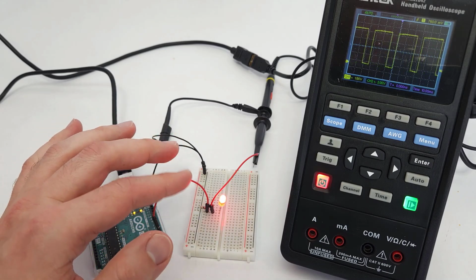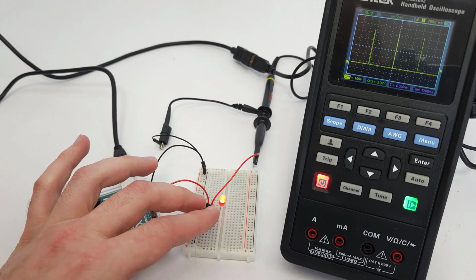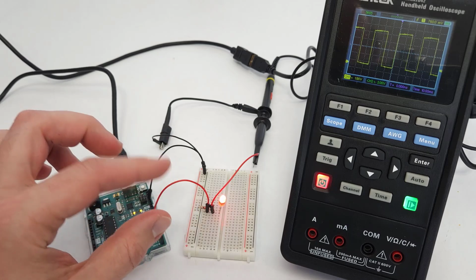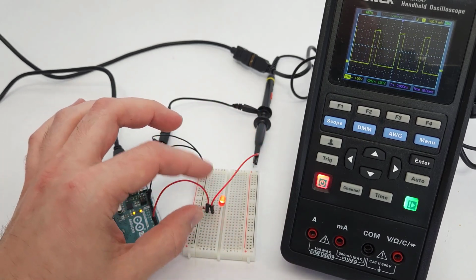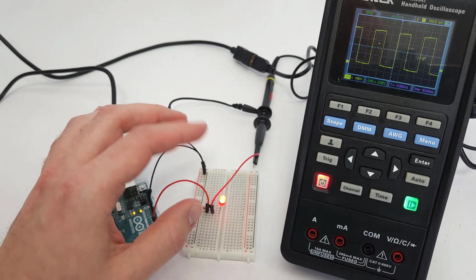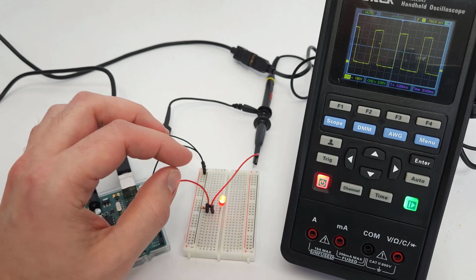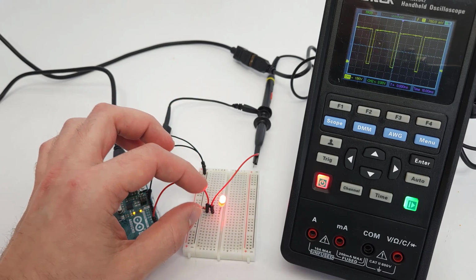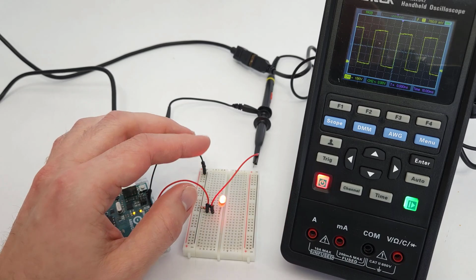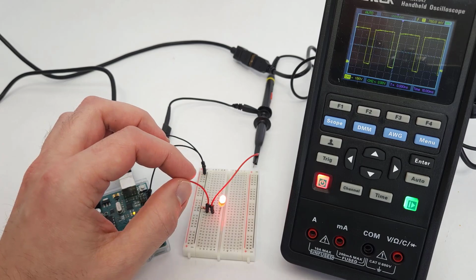It's going to look a little weird due to the frame rate, but now my human eye can actually detect some flickers. So it is staying on too long. If the goal is to give an illusion of just a continuous brightness at a certain level, it is now slowed down too much due to this larger prescaler value, such that the LED appears to be flickering to me. So in this case, the prescaler value is too large, and I would want to dial it back down.